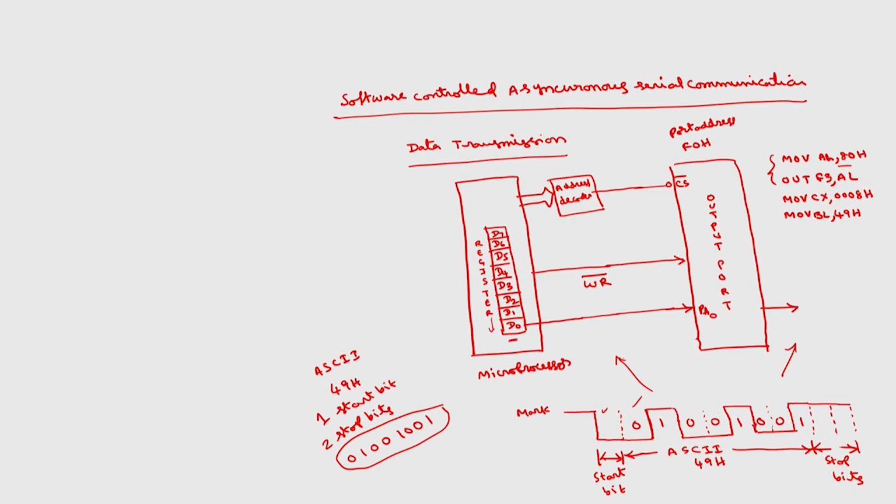First I want to transmit a start bit which is logic 0. So, for that I can take MOV AL, 00H, OUT F0H, AL, since port A address is F0H. So, what happens to PA0? All zeros will be transmitted, PA0 to PA7 becomes 0. Thereby a 0 bit will be transmitted, that is the start bit.